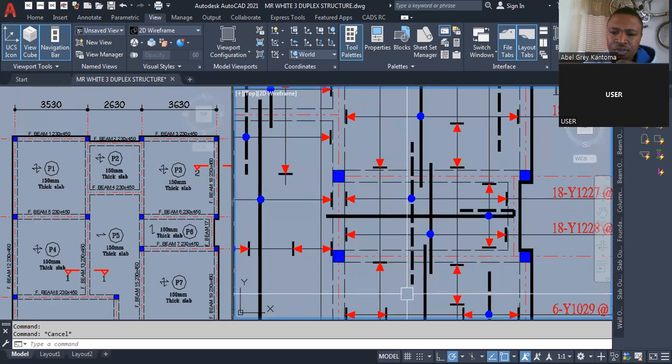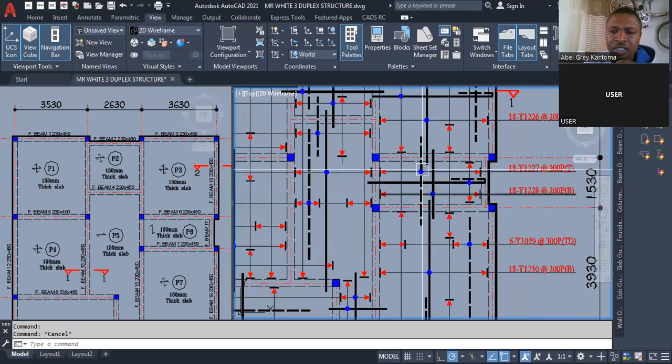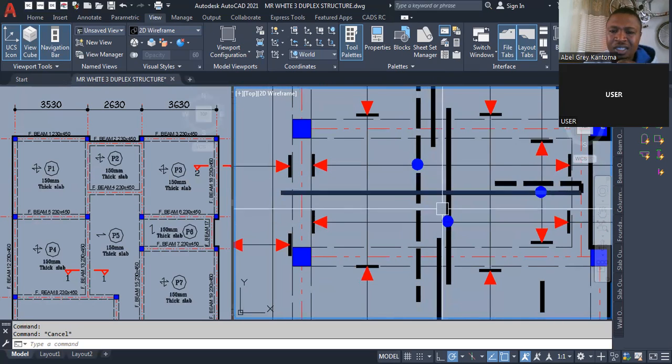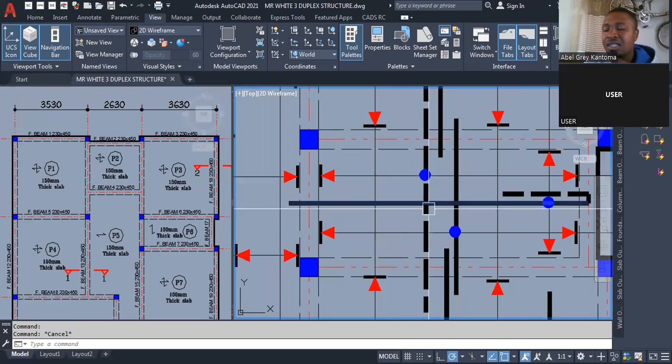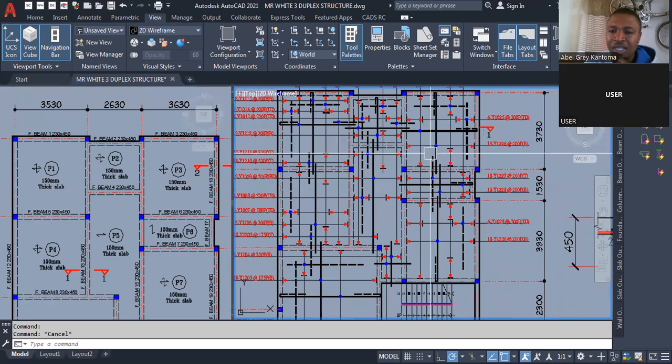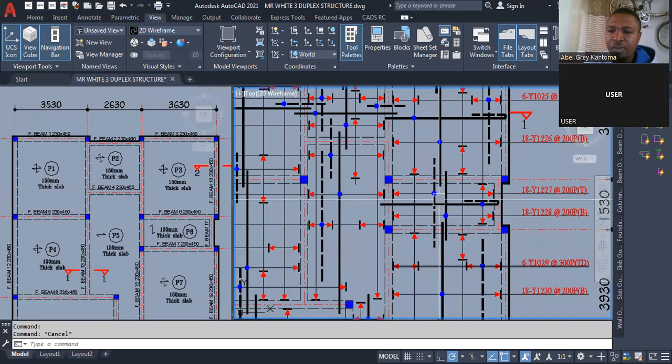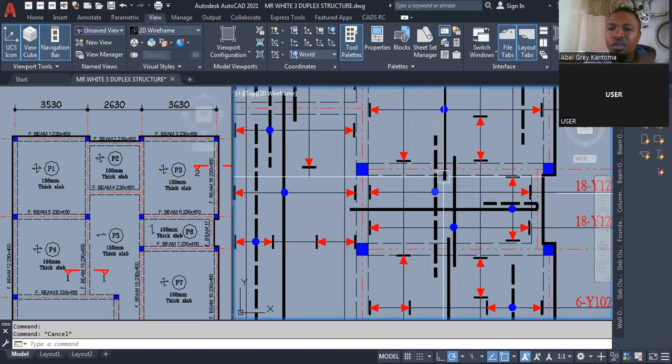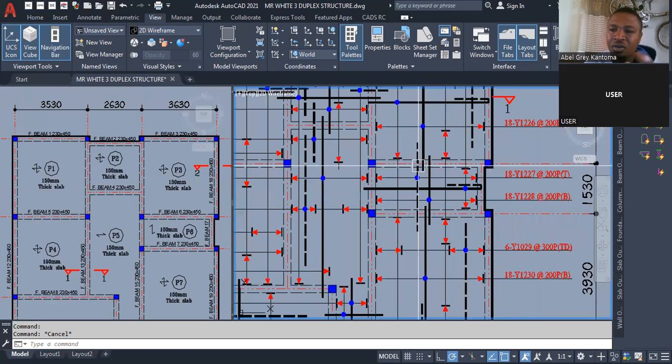So by the time you bring out the quarter of this, the quarter of this, and then at the long run, you may see that the space remaining is not that much. So that was why they spread this top bar across the two beams. But it boils down to your years of experience, site experience and all that.